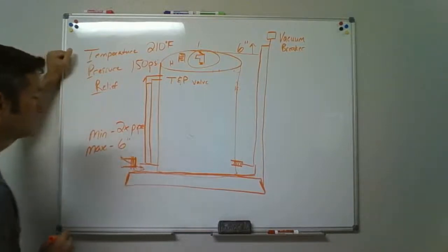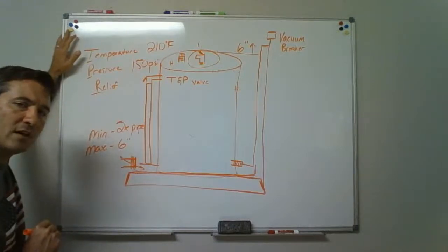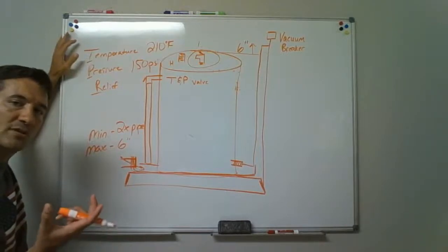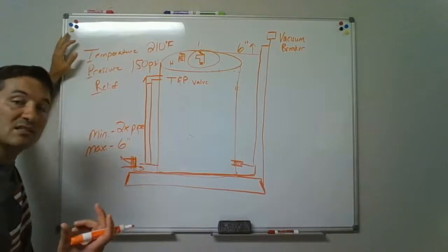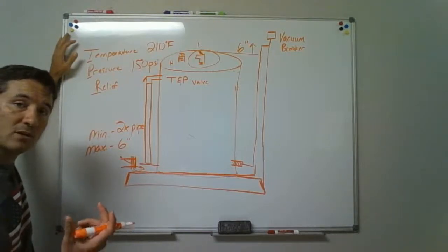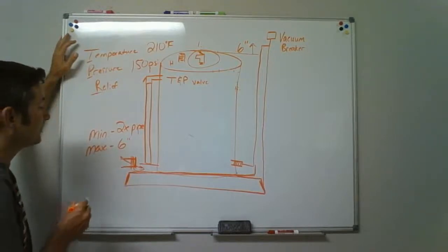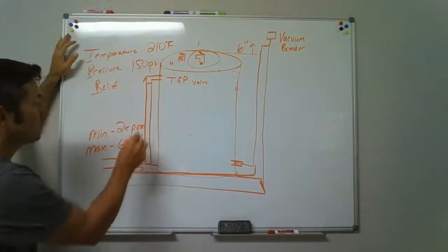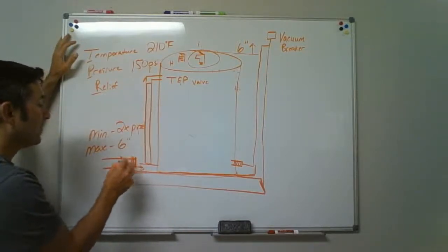Sometimes you'll see pans with PVC drain fitting adapters. You can't use those. It's got to be able to handle the hot water. So if you buy one that's got a PVC, if it's going to be inspected, you've got to toss that thing away and buy at least a CPVC, chlorinated polyvinyl chloride. It's allowed to handle hot water, something that's made for it. And then we run that and we can discharge that off. So we can take our TMP valve, discharge it into the pan, and then the pan drain can handle it from there.